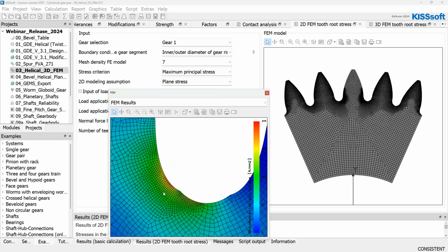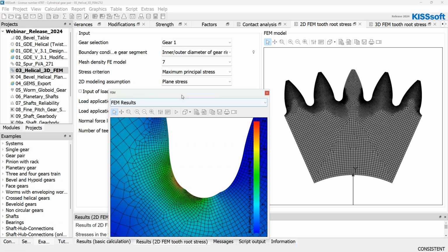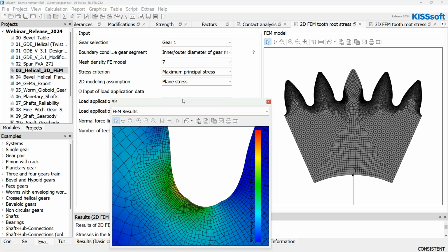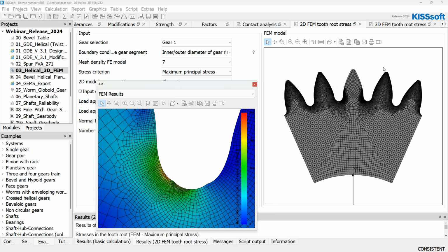And indeed, we can find that the grinding notch generates higher stresses than the root area, which was used for the design calculation as per standard. So in this case, the design engineer needs to pay attention, especially to either the grinding depth, the grinding stock or the tool radius, to avoid higher stresses.